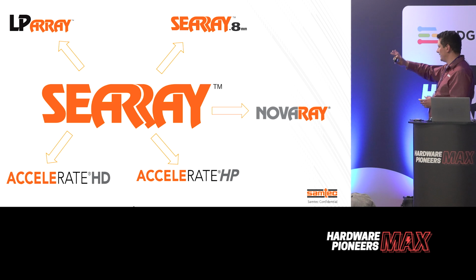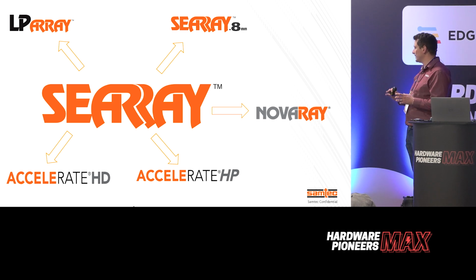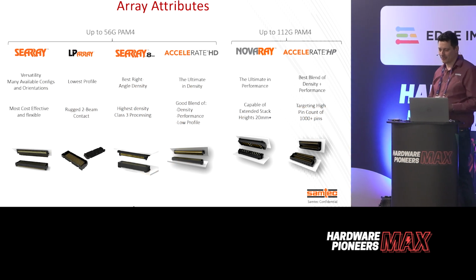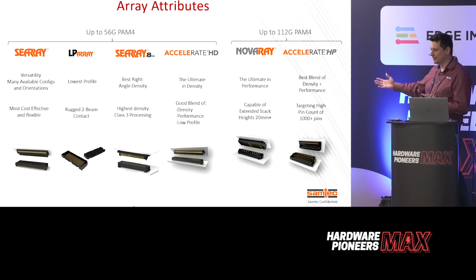And a completely different beast is the Nova Ray. Nova Ray is not an open pin field. Nova Ray is a full differential pair. So the way that we manufacture it is 2 pins fully surrounded with a ground plane already. So this one is 100% focused into the extremely high speeds or high frequency RF signals on the differential side. So you can probably get more than 10 gigahertz of RF signaling over that kind of wall-to-wall connectors as well, which is quite impressive. So there is not a better connector, it's just a better connector suited for your application.